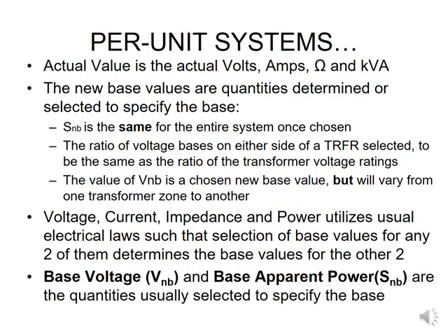However, the voltage that you are given as your base voltage for your calculations will not necessarily always be the same throughout your system. Why is that? Because we know that from generation all the way to distribution, our voltage is changing all the time. So, for example, at generation, in most cases you have your voltages at your transformer sitting at 13.8 kV.